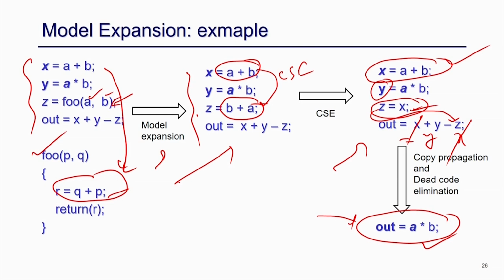in certain scenarios. Or maybe if that particular function has, say, 10 calls, we might just replace 1 or 2 calls, because if we see there is a very high chance of applying other optimizations in certain places, we can replace those calls, but I can keep the other calls there. So, I can use that function body for other calls, right. I can reuse that particular function body, or the hardware corresponding to the function body, for those other calls, right. So, there might be some trade off, and that has to be analyzed based on your application or the example